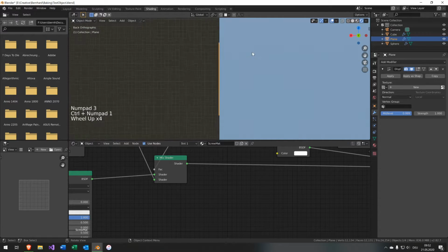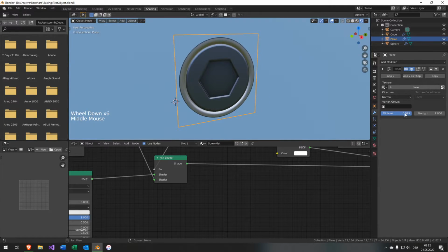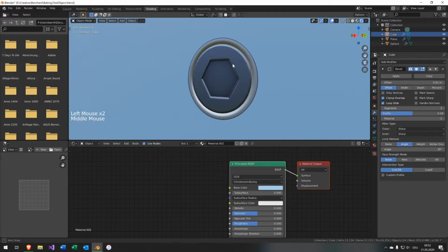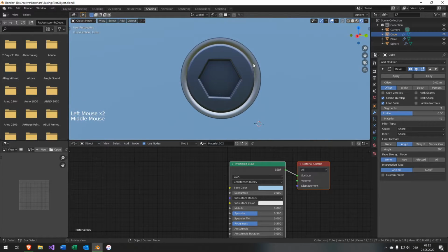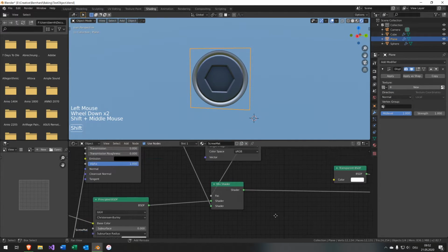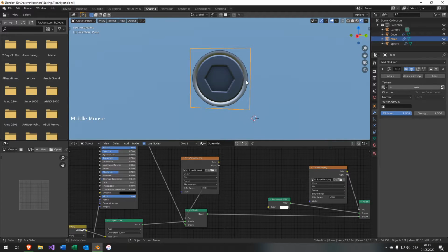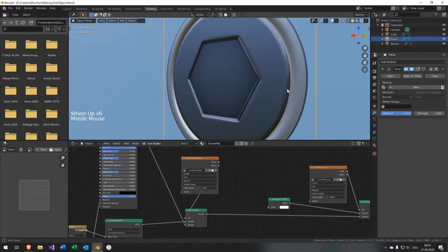And now I see the offset is pretty small. I can even put it further to the surface, so it's an even smaller gap between the decal and the object itself. The main purpose of this is to simply avoid shadows that are cast from the decal onto the object itself. So therefore we need to make sure that the gap isn't that big.